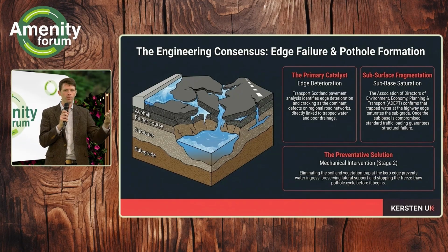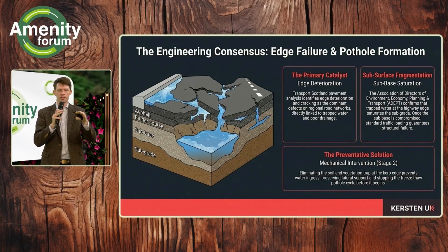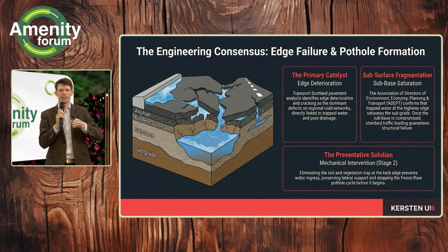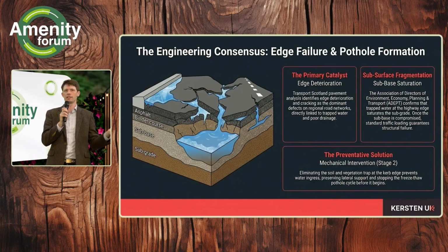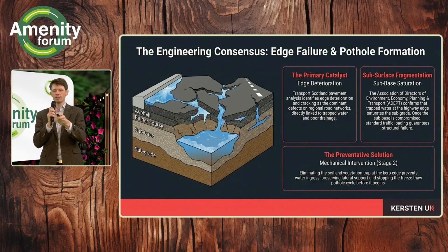And when you lose that support at the edge, you've lost the support for the middle of the road, and the middle starts falling away, and you get these hairline fractures up the middle of the road. Water gets into those, expands, and forces them out into potholes. So if you maintain the edge, you stand a lot less chance of having problems in the road.